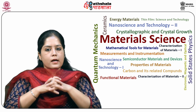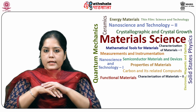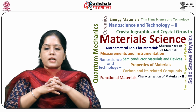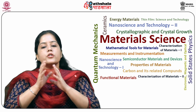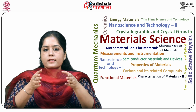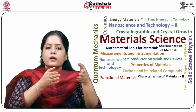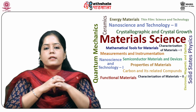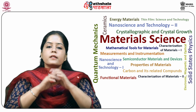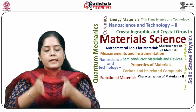The main reason is that, unlike BJTs, the various types of FET are characterized by a high input impedance, since the control voltage is applied to a reverse biased junction, a Schottky barrier, or across an insulator. So these devices are particularly well suited for controlled switching between a conducting state and a non-conducting state, and are therefore useful in digital circuits. They are also suitable for integration of many devices on a single chip.